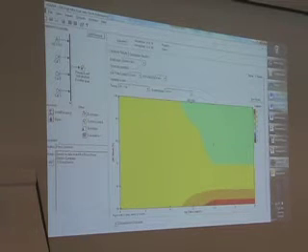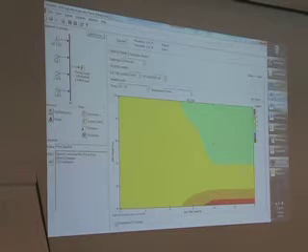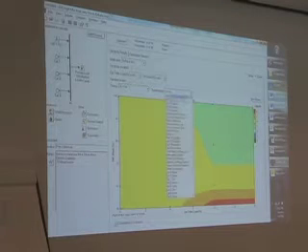So at low reserve requirements, it's actually increasing the optimum number of wind turbines simply because it's making the diesels less attractive. And at high operating reserve requirements, you have that problem I was talking about before, where the only way to achieve those higher operating reserves is to run the diesels, but you don't really need the power, so therefore you are throwing away more power. And so the optimum number of wind turbines drops to 3.